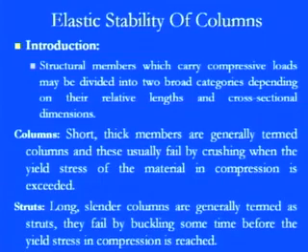And the second part is the strut. Struts are nothing but the longer, slender columns, which are generally termed as the strut. They are long, not thick, they are the thin part, and the theories have to be applied along the transitional way. They fail by buckling, because they have the longer length, so obviously buckling is an important parameter to check for failure. So they fail by buckling sometime before the yield stress in compression is reached.